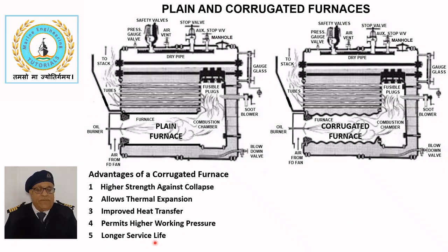Longer service life. Corrugations reduce stress concentration, thereby lowering the likelihood of fatigue failure over time. Better combustion efficiency. Turbulence created by corrugations improves the intermixing of air and fuel vapors, resulting in more complete combustion.